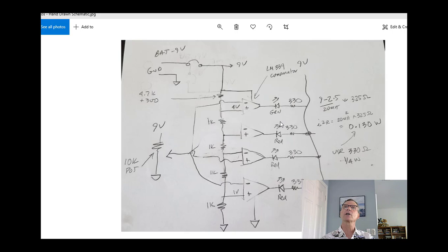Now let's look at our resistor here. So I did just a few little calculations here, and I said LED is going to be about 2.5 volts, and I'd like about 20 milliamps through it. How do I know that? Just experience, kind of experience you're going to pick up when you get into industry.